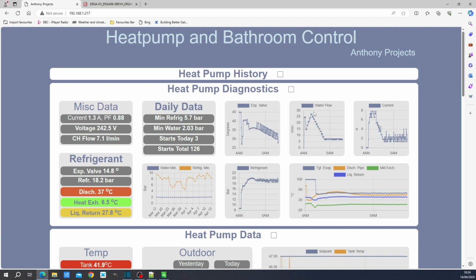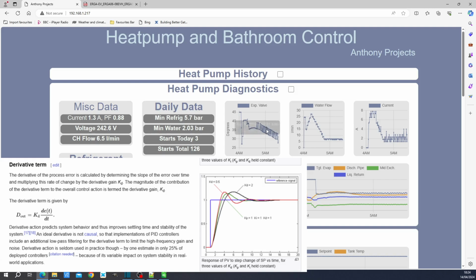You can see also here the water flow is gradually coming down, but the expansion valve is also gradually closing in. You know, we're at an expansion valve position of 35 to 30 degrees. This rapid movement here, this is what's known as differential control. So it's looking at the rate of change of a particular input, and it's reacting very quickly to a rate of change of pressure. So yes, there is a feedback loop going on here, but that feedback loop ultimately is created by having marginal flow conditions in the capillary tubes for your heat exchanger.